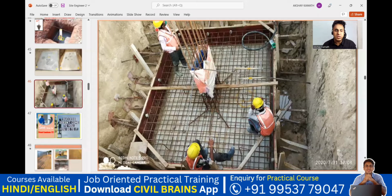Okay, I'll directly take you to the footing only. Before we do the concreting work, we do a shuttering work, something like this. So this will be 7 feet from this outer to this outer. Again, from this outer to this outer, it is 7 feet. And the depth, whatever you saw, right? It was 22 inches. Agree with me? So this particular depth will be 22 inches. Got it? So in this way, practically on the site, all these things will be done.